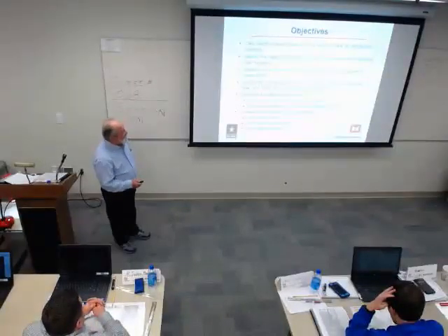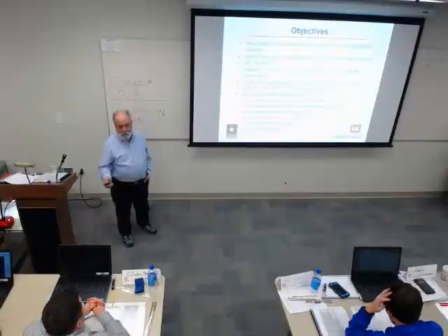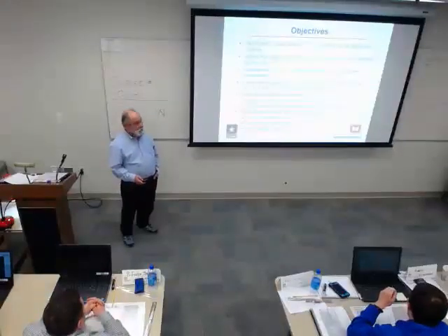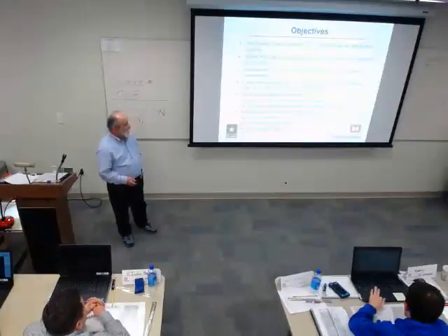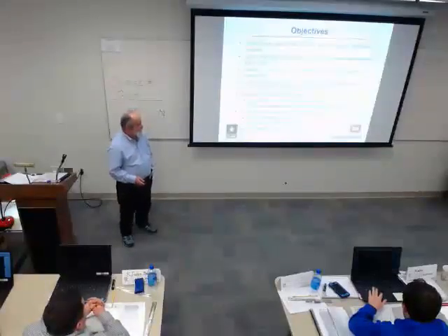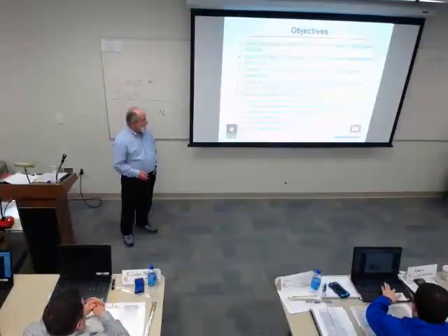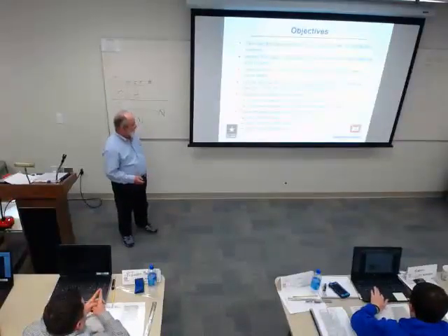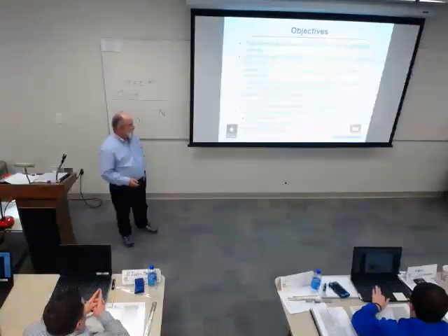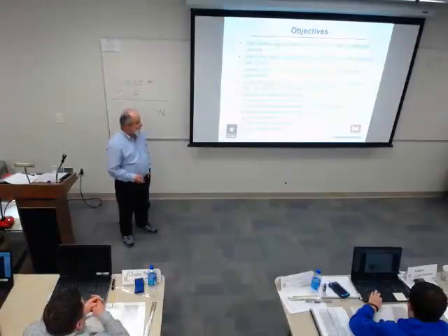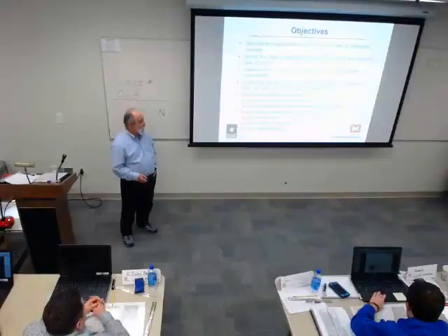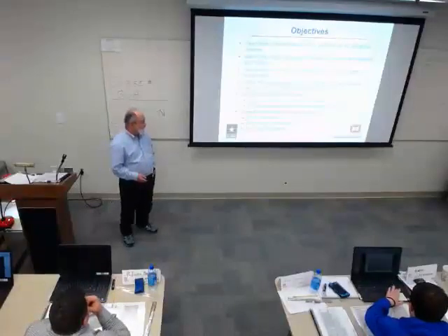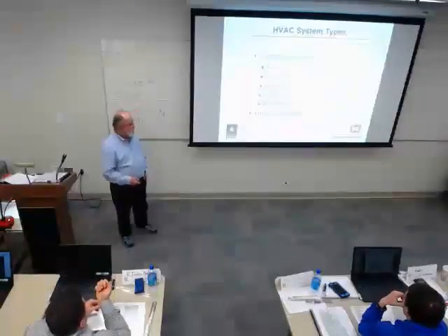We're going to be describing the major types of HVAC systems that we use in DoD. We're going to identify major components of the systems, describing their functions. We're going to look at the fan curve, equipment schedule, and equipment nameplate. We're going to locate the operating point of a system, given the fan curve, airflow, and static pressure to evaluate the selection. We'll note the differences between constant volume systems and VAV systems, pressure dependent and pressure independent systems, the most widely used standards for duct construction, pressure and duct pressure classification, and then fan testing and rating.